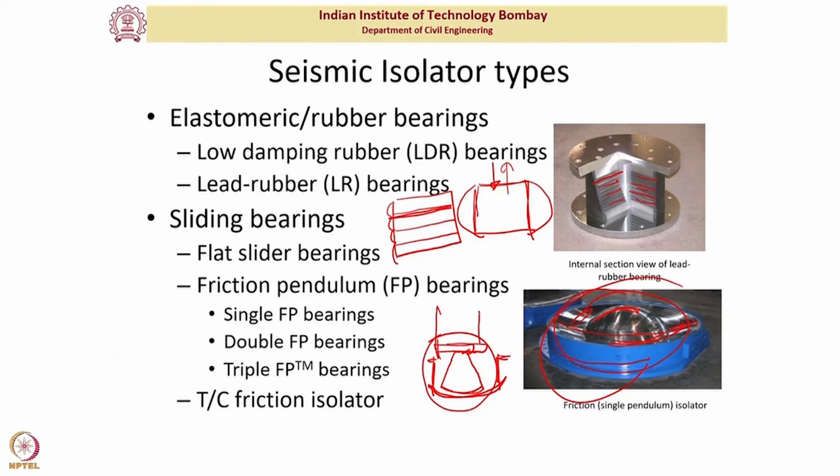What has been seen with natural rubber bearings is that they have less strength degradation or less environmental degradation over time. So that's why in the US they have almost shifted to natural rubber bearing. In Europe they are still using neoprene a little bit, but overall, if you replace neoprene with natural rubber, it performs much better for seismic isolation, of course.